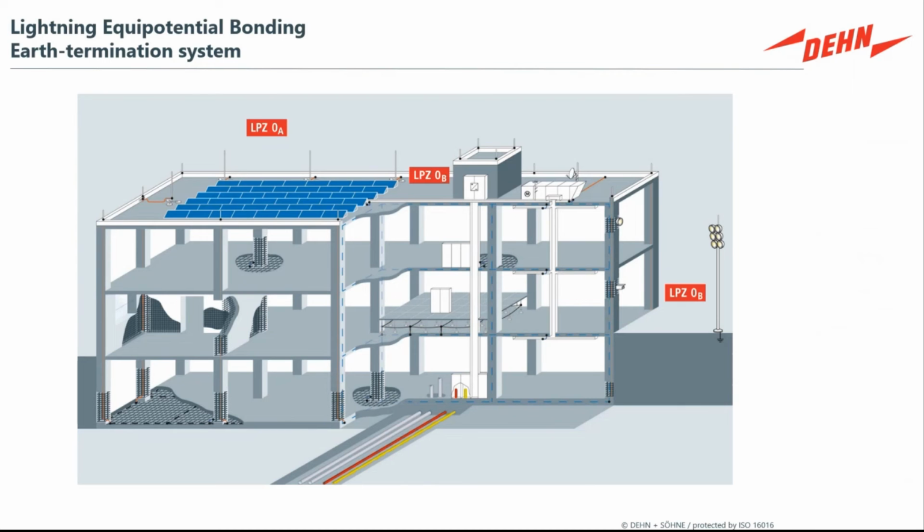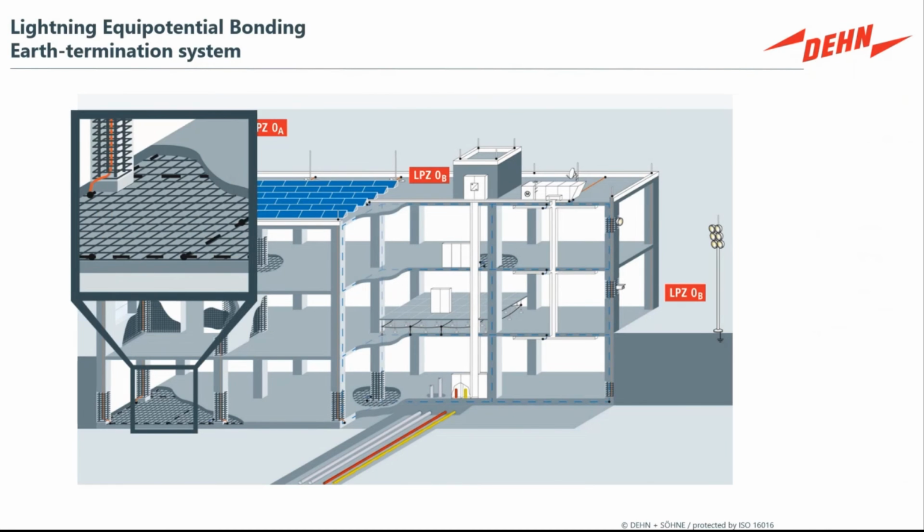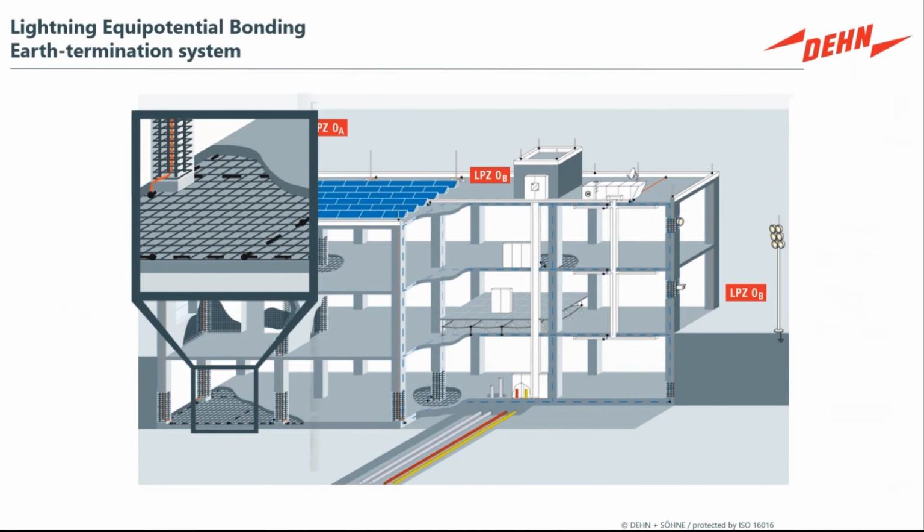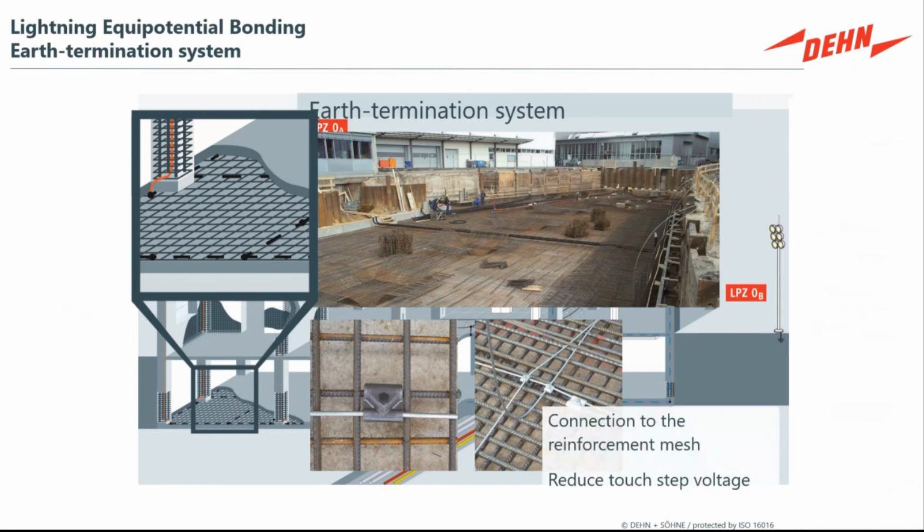So in a breakdown sort of imagery of what's going on at a site, you have an extreme level of detail. You can drive in and look at all of your foundation systems and just make sure that from the ground up, from day one, you built a green field with all the best methodology. And that includes lightning conductor systems built into the vertical pylons that are bonded into the steel and then bonded into the mesh at the base.